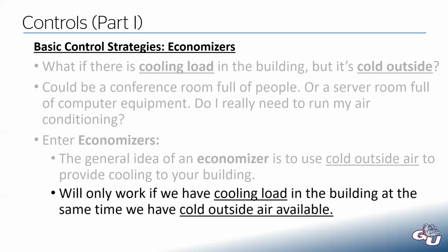This will only work though if we have a cooling load in the building at the same time we have cold outside air available. And depending on your building, there might not be a lot of hours where that is true. Because as it starts to get cold outside, generally you don't really have a lot of cooling load.